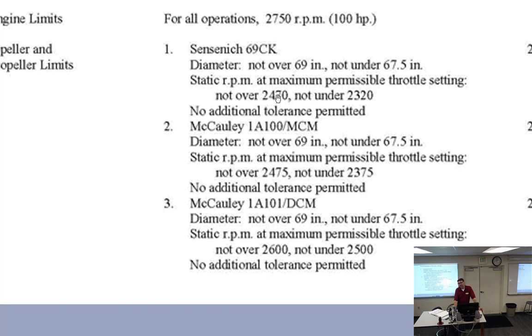Well, I don't live up in the foothills. I live down here, and I keep my airplane at McClellan with a 10,000-foot runway in my Cessna 150. So do I want a climb prop, or do I want to go fast? Go fast. I want to go fast, so I'm going to have it pitched more to 2320. Or maybe you just want it in the middle. Well, you get one in the middle. They usually come in like 3 different flavors.